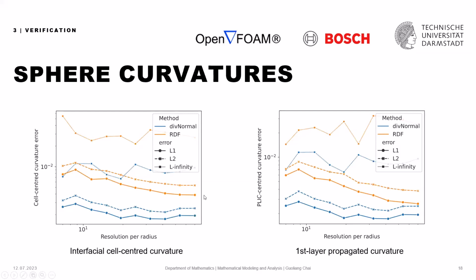But I'm only talking about the height function in the two-phase flow library. As I found out, they are very sensitive to the initialization of the alpha field. You have to initialize your alpha field using a very accurate method. If you initialize the alpha field using setAlphaField, then the height function is crap.